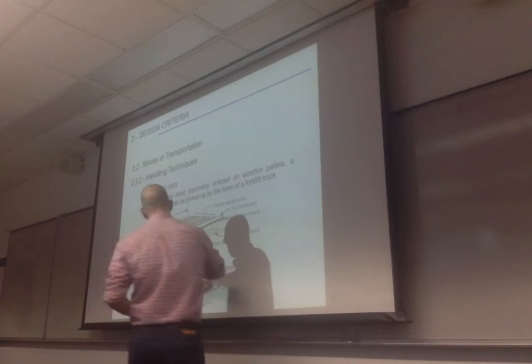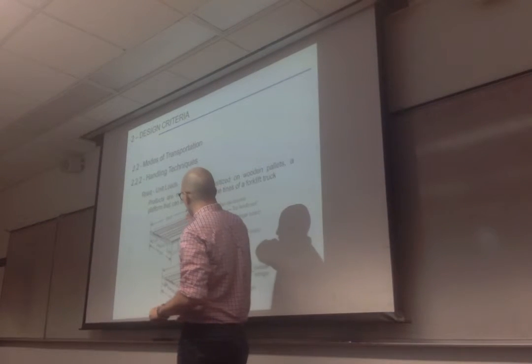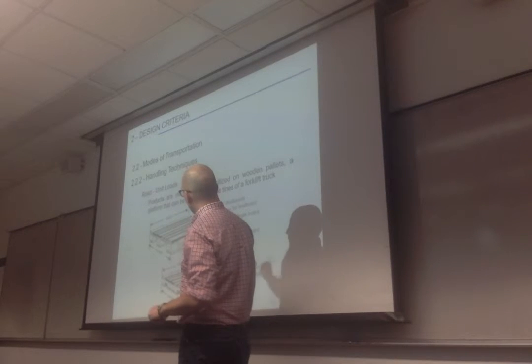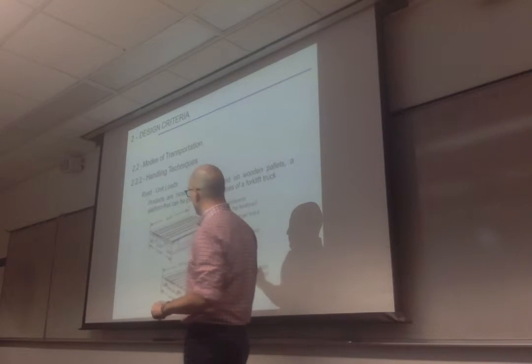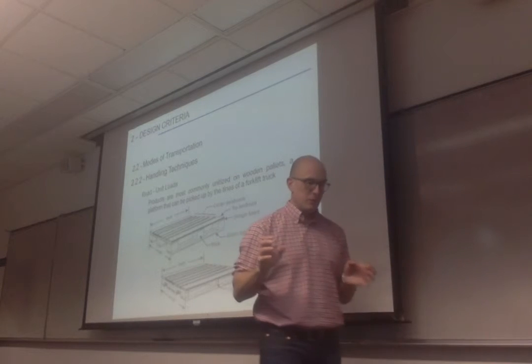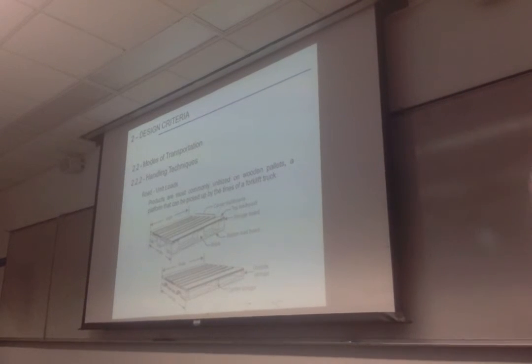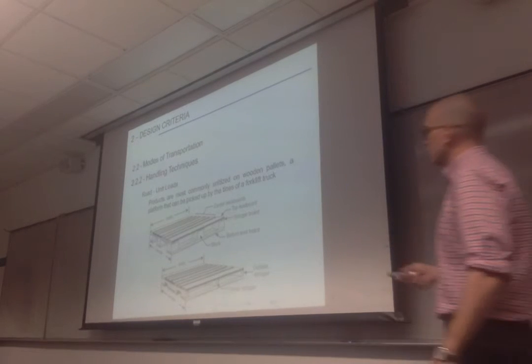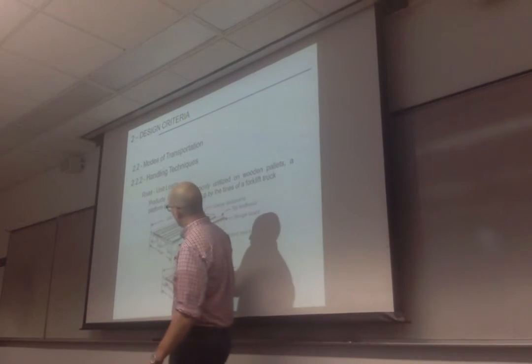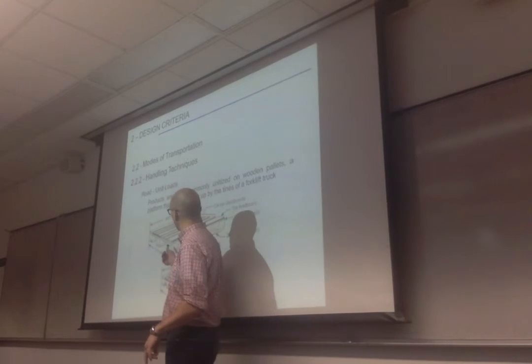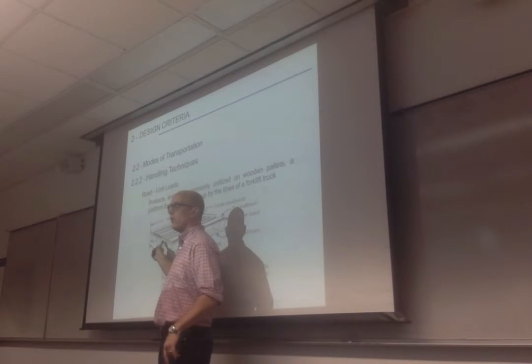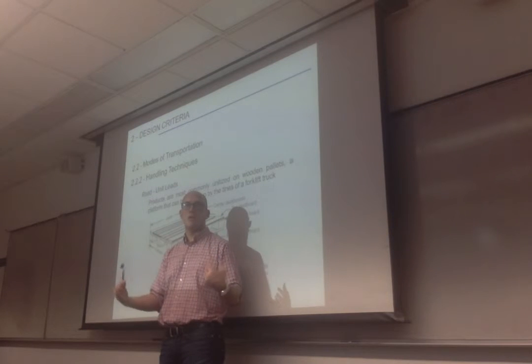And the deck board is kind of important, okay, how it's designed. And one of the reasons has to do with something we talked about last time: the strength of a corrugated box. Remember what we said? Where is the strength of a corrugated box? The corners, right? So on a pallet, what you want is the corners of your box, depending on the pattern you're going to be using, but you don't want it to fall in the hole. You want it to be supported on the deck.